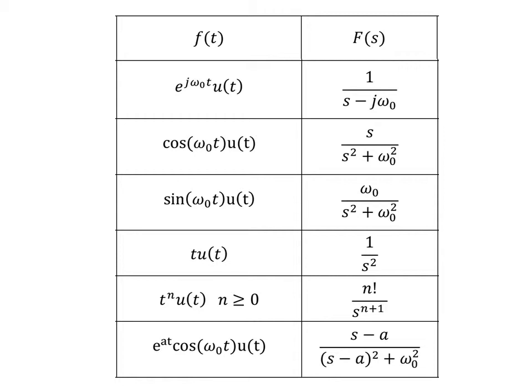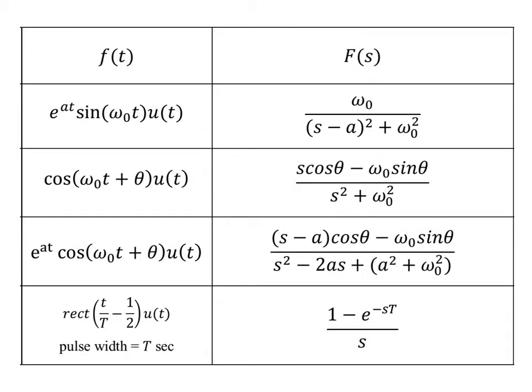This did not have a Fourier transform, but over a certain region of convergence, we may think of it as multiplying a ramp by a decaying exponential in order to make the Fourier transform exist. Well, that essentially is a Laplace transform over a specific range of sigma values. And we end with the last few entries in the table 9.1.